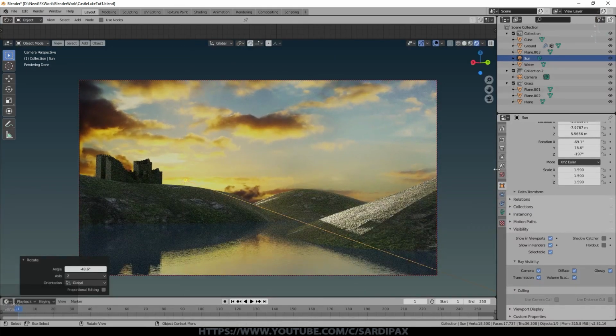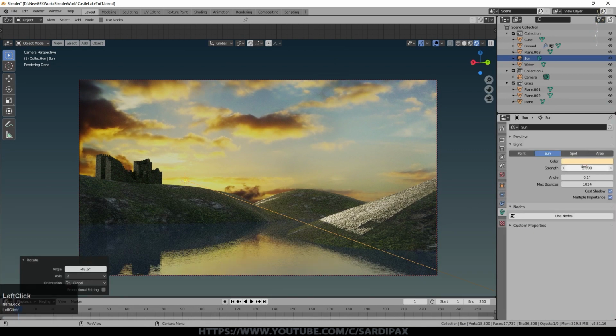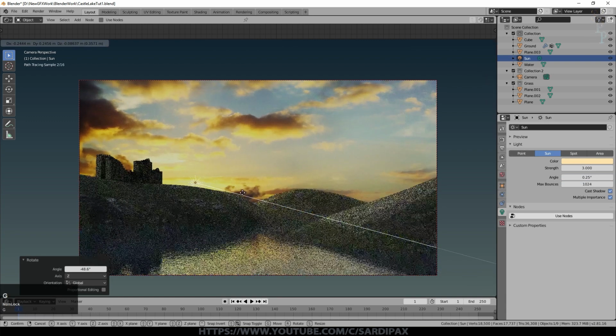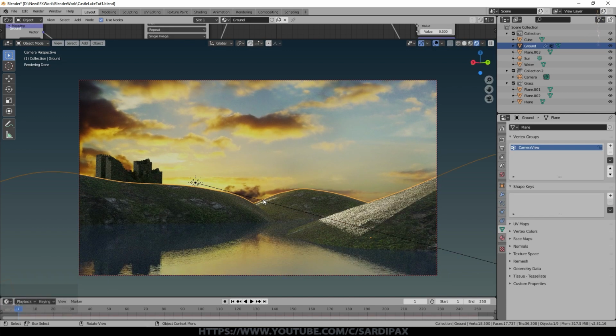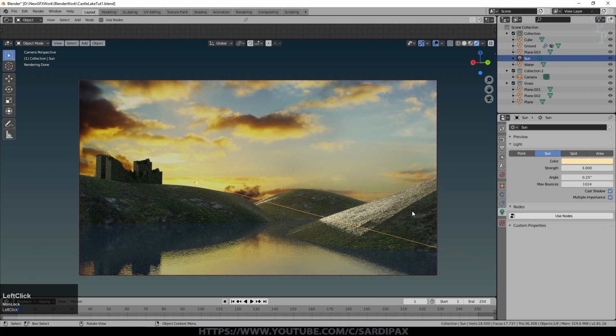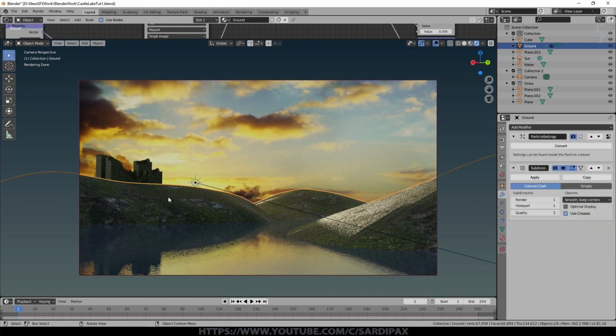And now you can see why I'm actually going to have to revisit the sun here and perhaps make the angle larger. We'll go for 0.25 because that's not a completely visible sun. It is slightly obscured by clouds, even though it's illuminating those clouds quite strongly. The other thing is, if you have a very strong sun effect, you can get some artifacts like this. It's very sharp.